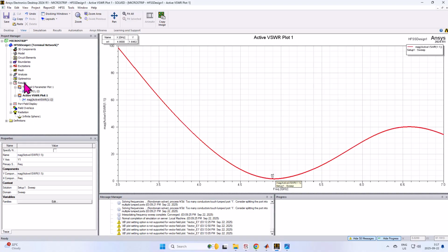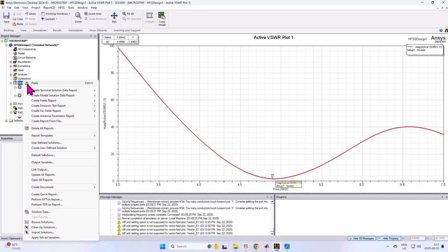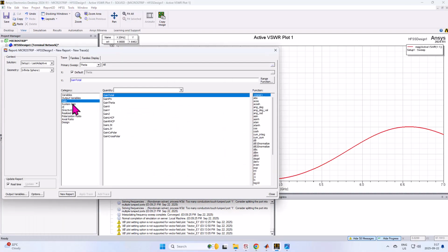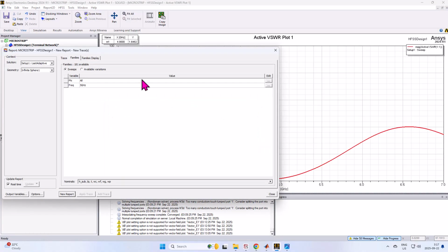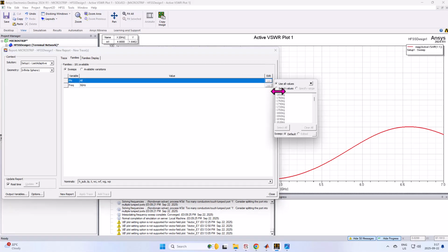So we saw them. We can see the radiation pattern. So we go to the far field report. We can see the rectangular plot. Yes, we can see here. So for the phi, I'm gonna click and select it as 0 and keeping the control go over to 90 and click on the 90.